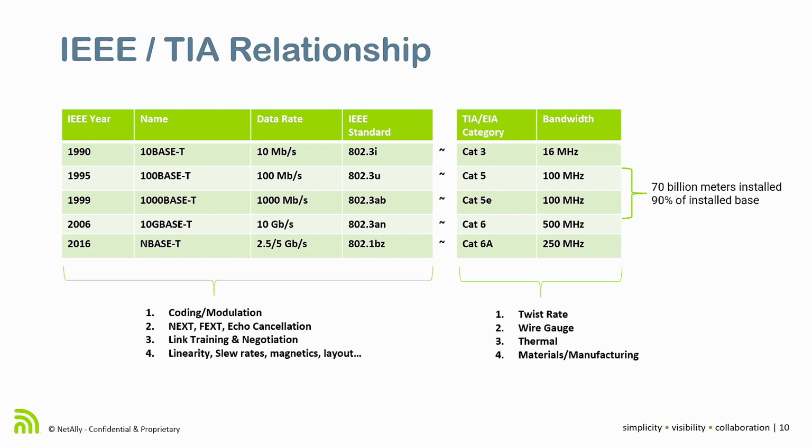On the other side, they're kind of chasing twist rates. I mean, there's a magic in taking two pieces of wire and twisting them, but the cable standards have largely been about twist rates, isolating the twisted pairs, and gauges. PoE brought in some thermal concerns, but to some extent it's a bit of a materials and manufacturing game, right?